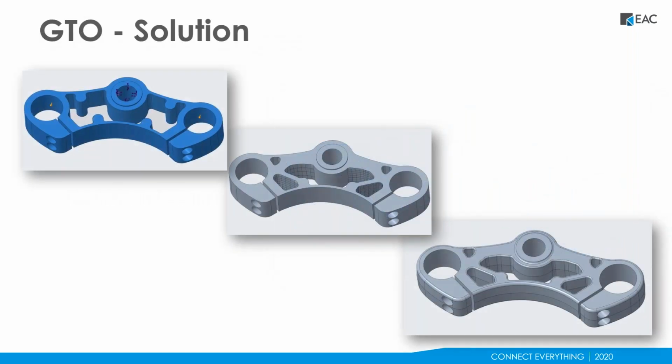Well, PTC has this generative topology optimization, right? So we're going to just abbreviate that as GTO. What we have here is some new capabilities that allow us to autonomously create more optimal designs based on some design requirements, things like boundary conditions that you might be familiar with in analyses, your loads, constraints, materials, but then also the manufacturing process. We can consider that as a function of the generative topology optimization.